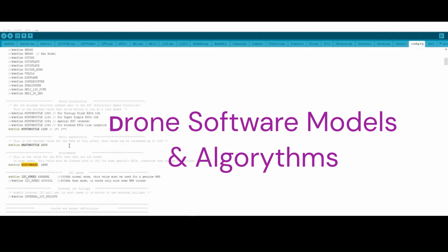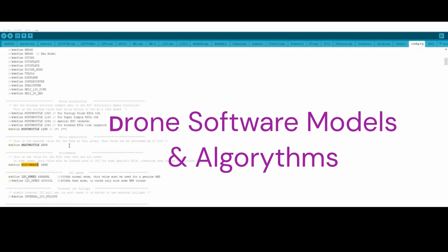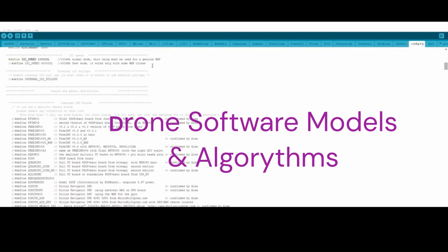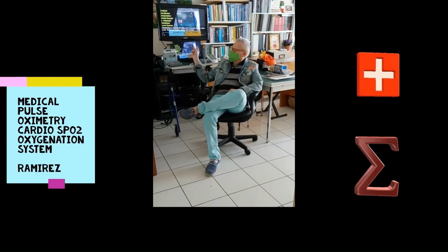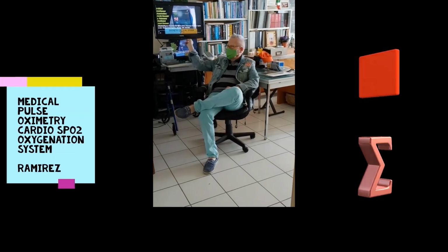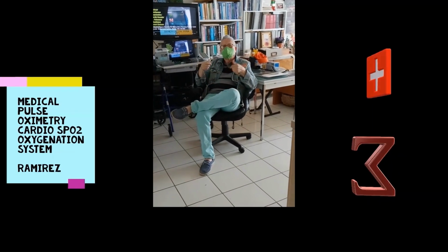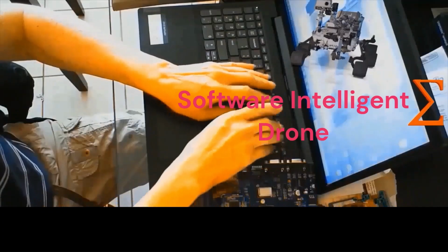But if you want more RPM, use smaller or mid-size propellers. If you want more stability for the smart drone, which will lift weights, then we'll use less RPM at the motor with more torque and higher pitch propellers.